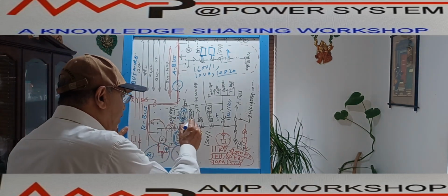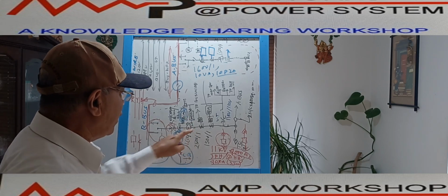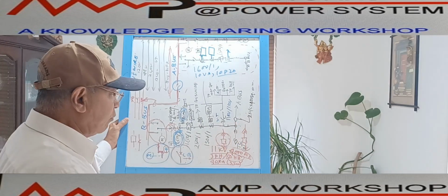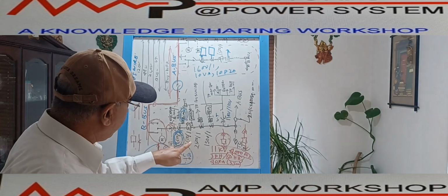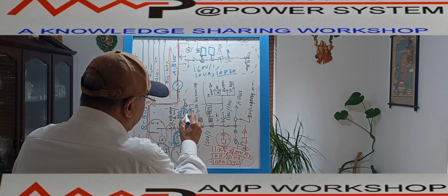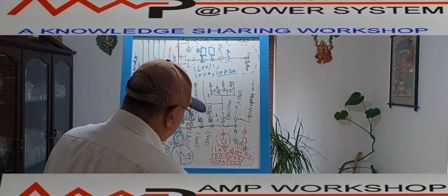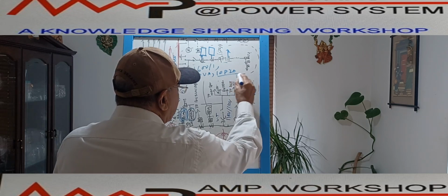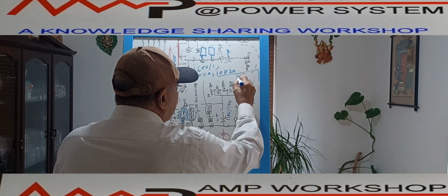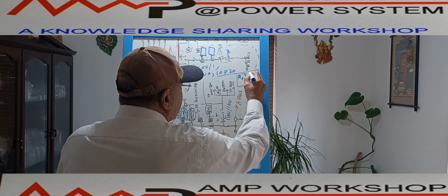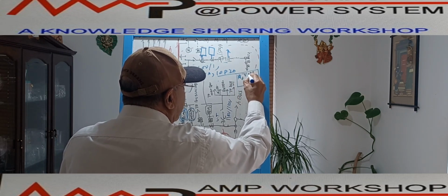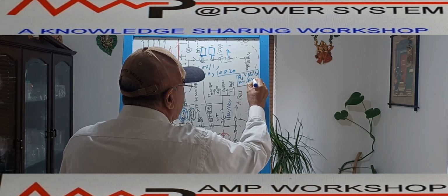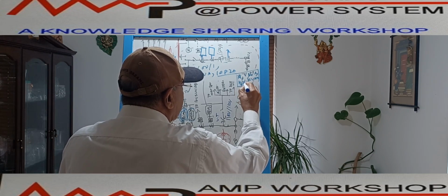Similarly, the multifunction meter has another CT, with the same ratio 1600/1. This ratio will be decided based on the generator rating, which we have already calculated. Similarly, the multifunction meter block will also be shown in the same way. What about the various functions inside the multifunction meter? Inside the block we write, suppose, ammeter, current measurement, voltage, then VA or kVA, then kilowatt, then kVAR, then power factor, then frequency.